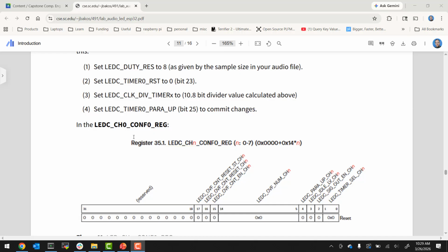24 bits, right? And sending 24 bits, even though it's like 1.25 microseconds per bit, and you're sending 24 of them, so whatever 24 times 24 plus a quarter of 24, which is what, 6? So 30. So 30 microseconds. So it takes 30 microseconds to send one color to the LED strip, right? You guys with me? 30 microseconds is a pretty long time for a processor that's running at 200 megahertz, right?